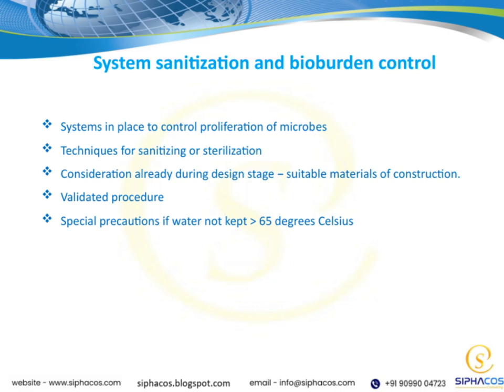Speaking of procedures, it's vital that we follow validated methods for cleaning and sterilization. Validation ensures these procedures are reliable and effective, providing confidence that microbial levels are kept in check. Another important point is the need for special precautions when water isn't kept above 65 degrees Celsius. At lower temperatures, microbes can survive more easily, so we have to implement additional measures to ensure proper microbial control